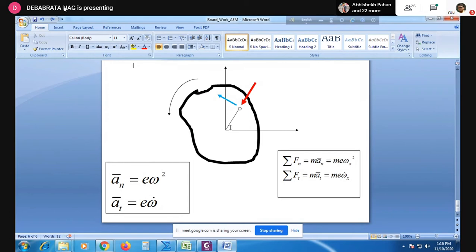Whenever there is a periodic change of bearing reactions within the journal, then what happens? The oil film that is present in the bearing will generate a phenomenon which is known as oil whipping. In the entire shaft there will be oil whipping, oil induced vibration will be produced in the entire system, and the entire system will vibrate like anything.